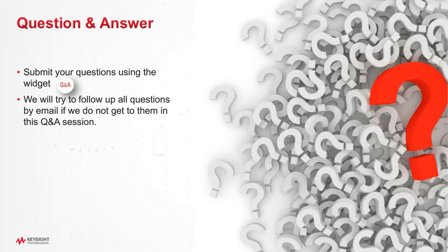Very good question. You can bring your algorithm, whether it is in the form of C++ code or MATLAB or HDL. You will be able to bring that code into SystemVue as a model, and when you simulate, you can actually put breakpoints in your code, and you can debug as the simulation goes on. You can debug the variables in your code and then modify it, correct it, enhance it, or fix anything that's not working. So SystemVue is very conducive to bringing your own algorithms.